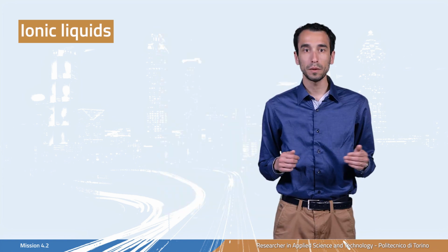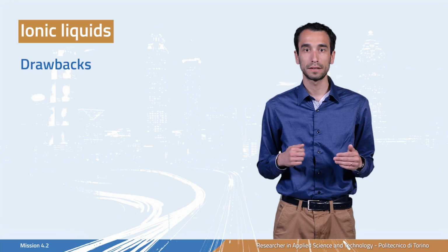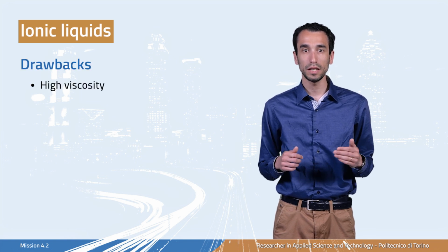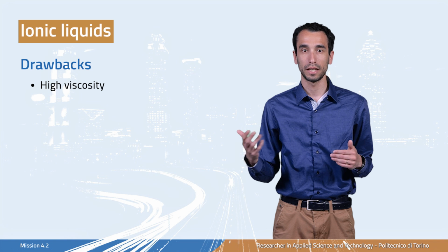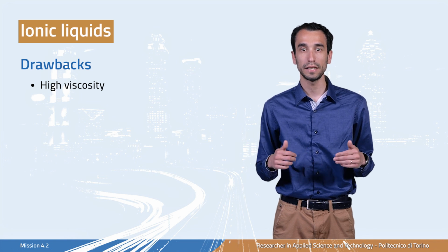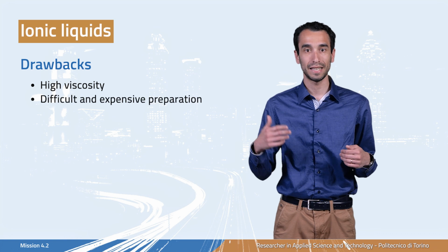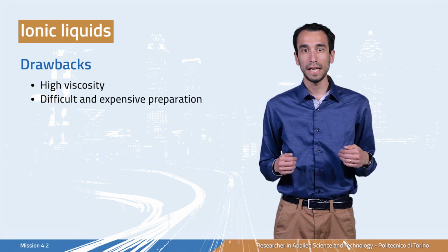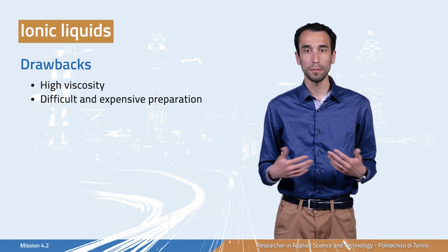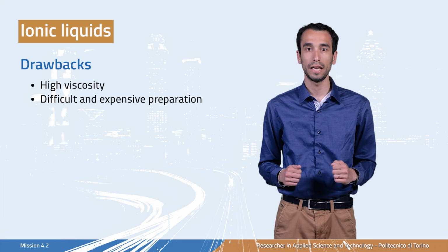However, ionic liquids suffer from some drawbacks, such as the high viscosity that reduces ionic conductivity and causes higher internal resistances within the battery, and their difficult and expensive preparation that makes their use still economically unfeasible for large-scale commodities.